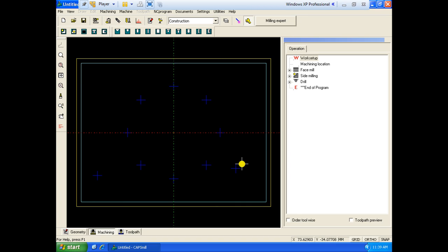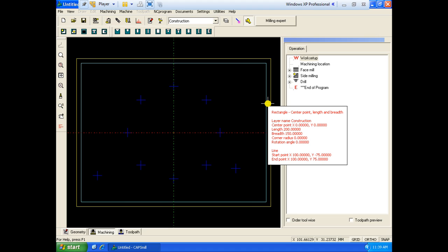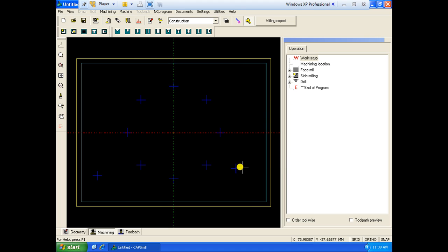The hole size will be less than the metric size. Here 8 mm is the metric thread, the pitch is 1.5. So what you need to do is 8 minus 1.5, which is 6.5. You need to drill a hole of 6.5, and the remaining 1.5 pitch will be obtained by the metric thread, okay?